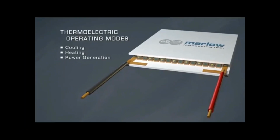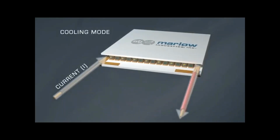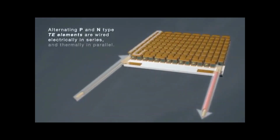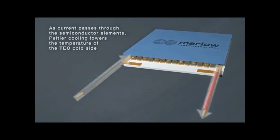In the production of thermoelectricity, there are three types of operating modes: cooling, heating, and power generation. Alternating P and N type TE elements are wired electrically in series and thermally in parallel. A current passes through the semiconductor elements. Peltier cooling lowers the temperature of the TEC cold side.